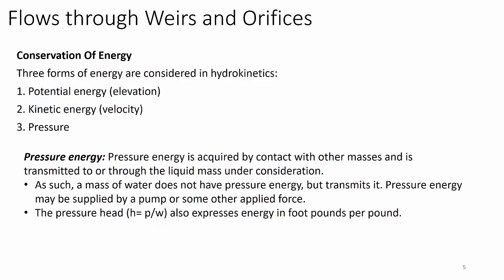Pressure energy is acquired by contact with other masses and is transmitted to or through the liquid mass under consideration. As such, a mass of water does not have pressure energy, but transmits it. Of course, that's how hydraulics work, is that you push water in one cylinder and it goes through a pipe or conveyance under pressure, and then it releases that pressure in another cylinder. That's how the brakes in your cars work. That's a transmission of power.